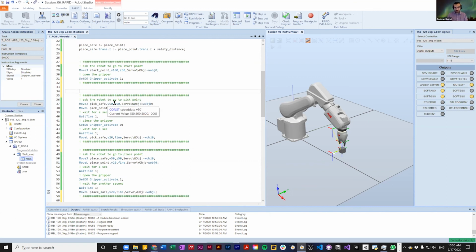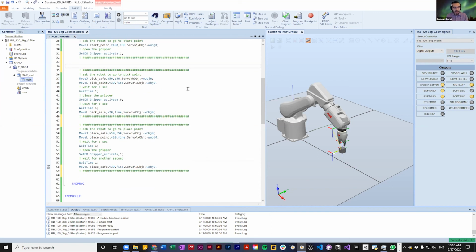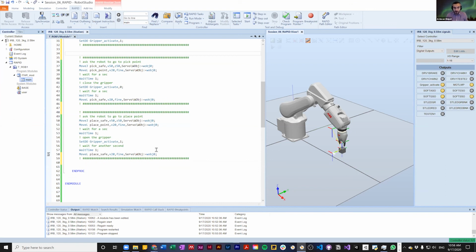So in Robot Studio, in order to organize these things, we are using procedures. You have seen procedures. Main is a procedure here. Those path 10, path 20 that we used to make are also procedures. And we can organize our code in procedures. So let's do that. I'm going to make a procedure. To make a procedure, you just type PRO, or whatever, the beginning of this procedure, and double hit tab. And then it populates this structure of code for you.